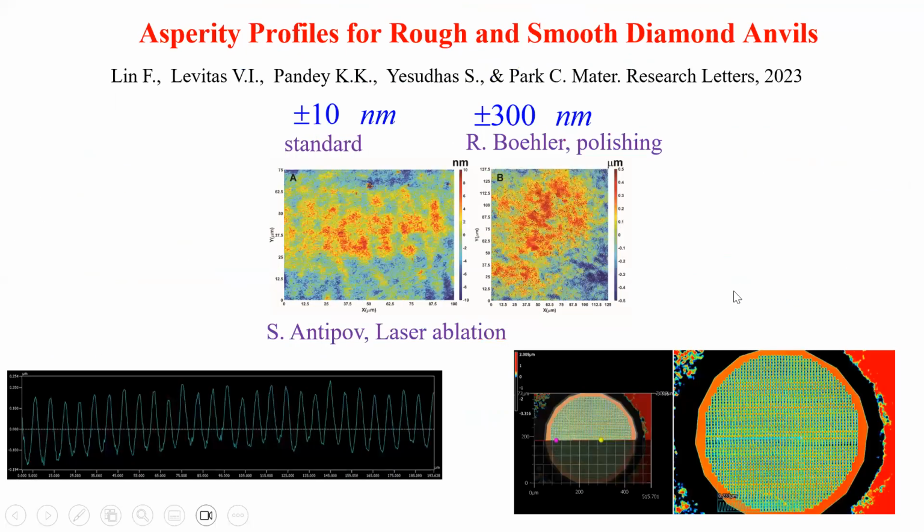And friction plays a crucial role in high pressure research because it determines pressure distribution and maximum possible pressure. The usual assumption is that it's equal to yield strength in shear, and this is used in methods to find pressure dependence of yield strength in shear. Because we can determine all stresses, we found that actually friction stress is even less than half of yield strength in shear. That means that known methods have significant error.